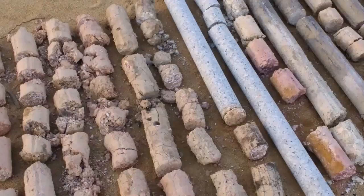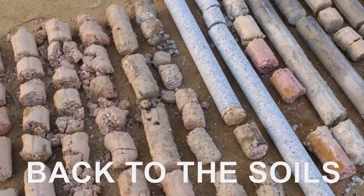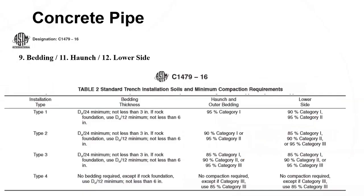All right. We talked about soils last time. Let's go back to the soils and talk about those again to make sure that we're understanding that. In sections 9, 11, and 12 on concrete pipe, it talks about the different types of installation. So here you have on the left-hand side of the screen your type 1, 2, 3, and 4. If you remember, the type 1 is your really stout, really strong installation, right? It's got your A1, A3 material compacted to a 95% compaction, right? It's a really good installation.